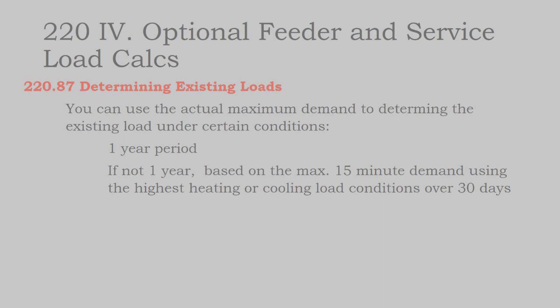Now, where this is relevant to on site power systems is sometimes your utility will establish a maximum size that you are allowed to interconnect to the grid based on your 1 year load usage. And I've heard that, it's kind of interesting. You go to net metering, they say, well, you can't have a system that will offset more than 100% of your energy use. But I've also seen requirements where they also say you can't do an array that will offset substantially more than your power.